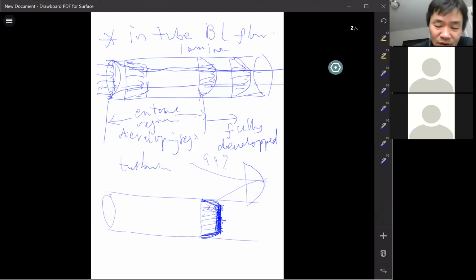Actually, if you look at the average velocity, you probably would like to deal with turbulent pipe flow. It looks like a straight line here, like the velocity is a constant. Although there's a region up and down where the velocity is smaller, most of the place seems like a uniform velocity, if you just look at the average mean velocity. So calculation-wise, if you only deal with the mean velocity, the time-averaged velocity, then the problem is simple. We usually use that velocity as the average velocity, basically.